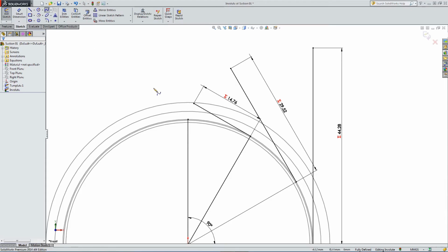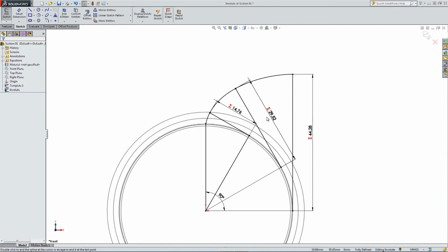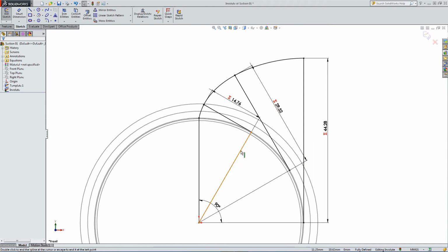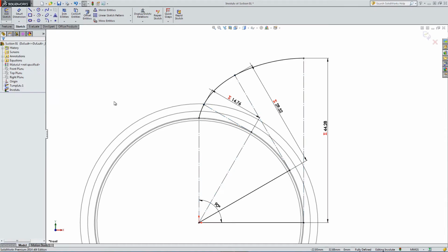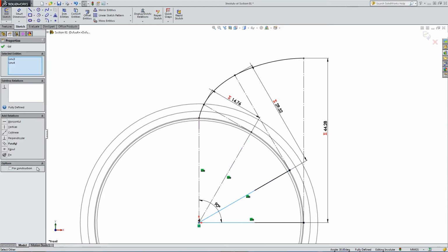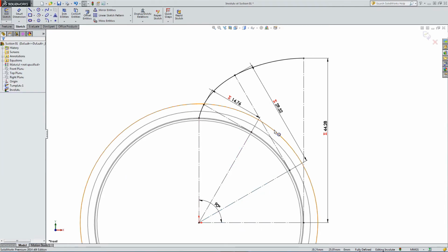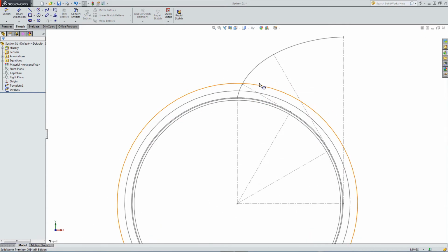So now we can form the involute from a reference point to our second, to our third, to our fourth, and we'll stop there. So we basically cut our circumference into 3 sections. We've made tangents and we formed our involute circle. So let's just make everything here into construction geometry apart from the involute. And that is the beginning of our involute for our gear tooth profile.